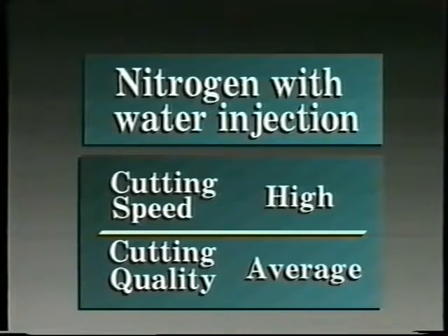After having had a look at a number of installations elsewhere in Europe, we understood that underwater plasma was a superior method, both in terms of cut tolerances and the working environment. Nitrogen plasma gives a high cutting speed, while the cut quality is average.